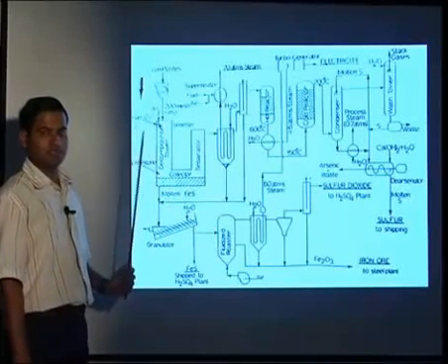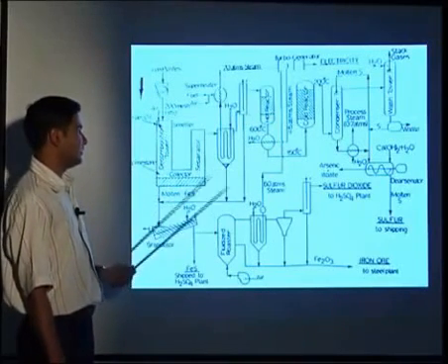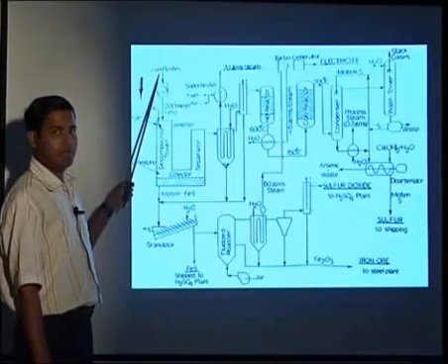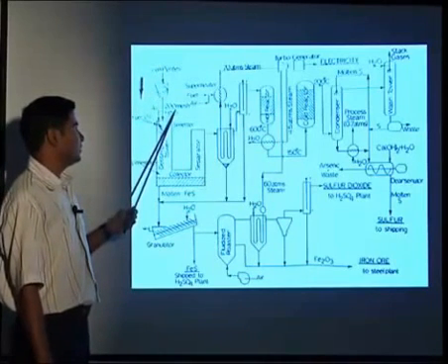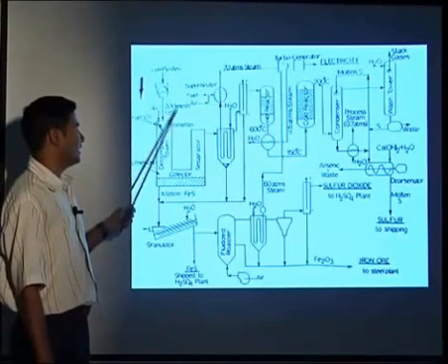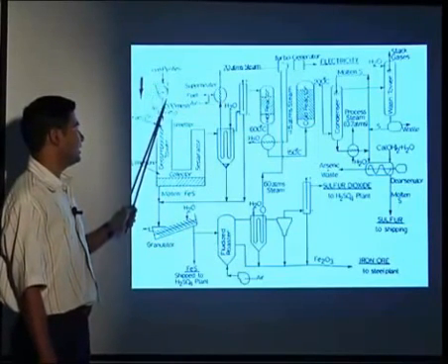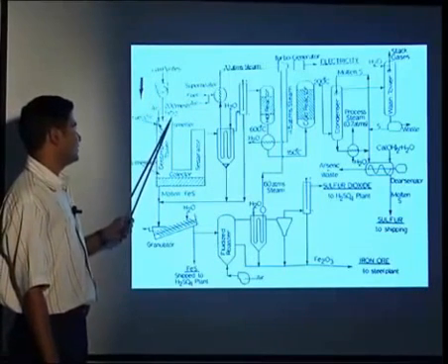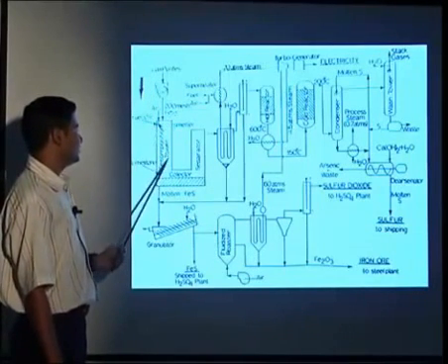So this is the process flow diagram of obtaining sulfur from the iron pyrite. Here we are using 200 mesh, so we are grinding in a rotary kiln to get the iron pyrite, and we are passing it through the 200 mesh. So here FeS2 we are feeding to the decomposition tower.